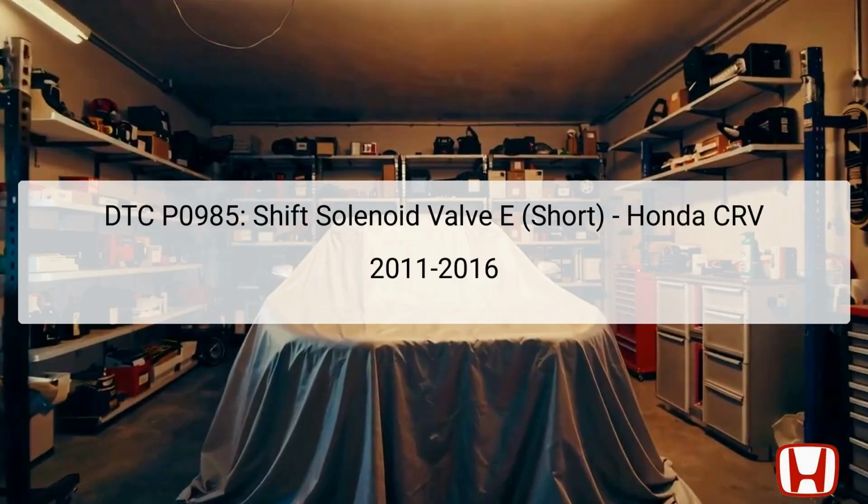The diagnostic trouble code DTC P0985 refers to a problem specifically with the Shift Solenoid Valve E in the Honda CRV models from 2011 to 2016. This error indicates a short circuit in the electrical circuit associated with this solenoid, which is fundamental for controlling transmission shifts. Understanding this DTC is crucial for diagnosing transmission issues, since this error is purely electrical and not related to any mechanical malfunctions within the transmission.